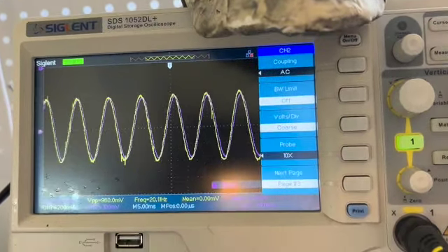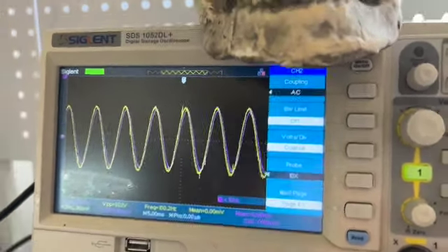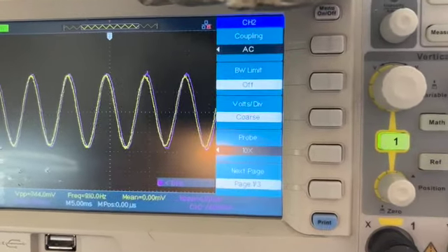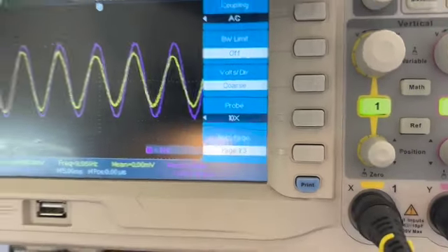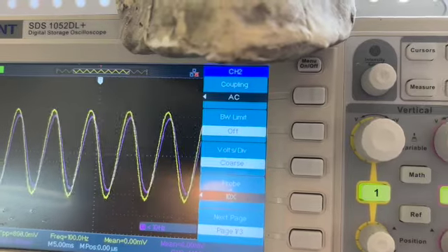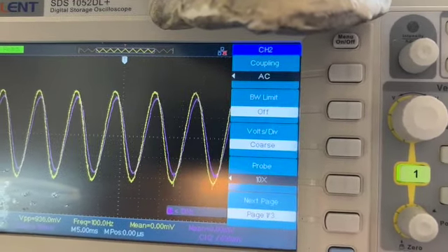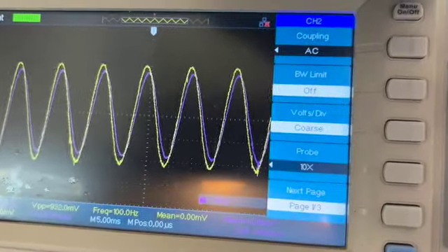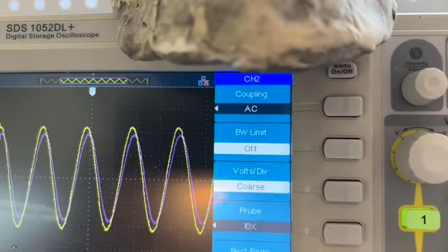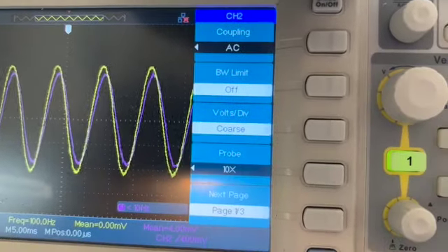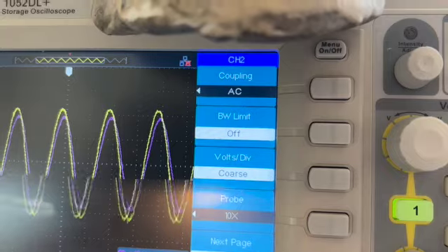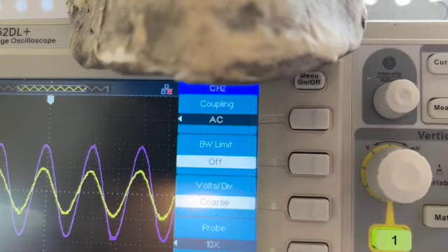Now we're at 100 hertz. We're in the same scale, right? Almost half the signal, and we're really close to the frequency that we were looking for. Little interruption there from me tapping things here. About 50% is what we're looking for when the impedance of the inductor is the same as the impedance of the resistor. We should see these at approximately 50%, right?